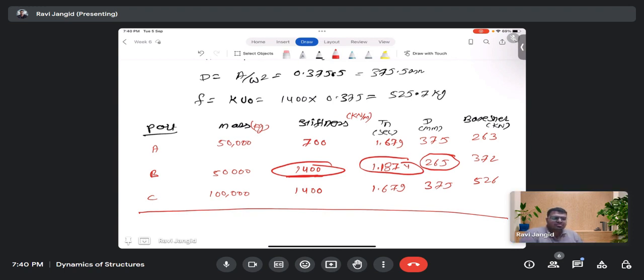Here, base shear, how can we call it a demand? Because it all depends on properties, right? K and L. This much, for this much it has to be designed. So it is a demand. You cannot design for less than this because you already considered the scaling factor. So you are considering the design value, the design base shear. It's a requirement. It's a demand actually. For this, you have to design the stiffness of the element, column. The structure needs to define the size of the section on the basis of that demand, to satisfy this demand.